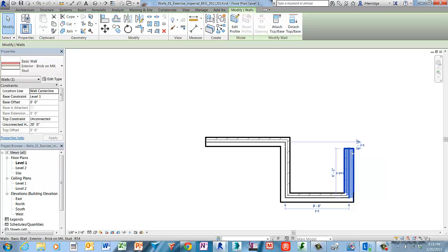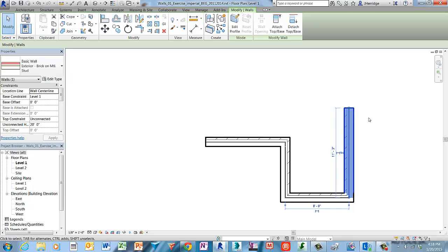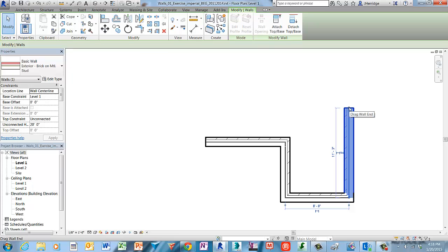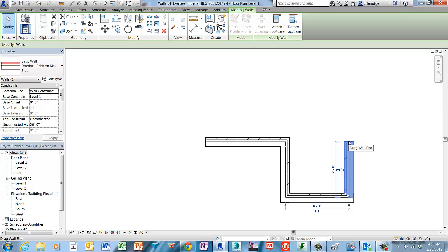Let's pull that just back from there, and then using the shape handles again, go ahead and drag that point above the first wall that we placed. And then let's reselect that wall. Select the shape handle again and drag it back to acquire that alignment snap with the first wall that we placed. Next, we'll draw a series of walls using the chain technique.